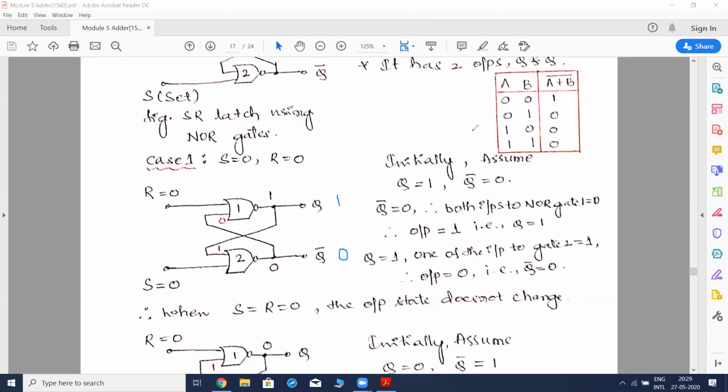So now from this NOR gate truth table, where we have to start our analysis, we have to start wherever 1 is present. So that means Q here is equal to 1, is it not? So now we have to start from this one. So our input here became 1, irrespective of the other input, is it not? So we know that it is 0. Even if it is 1 also, there is no difference for us.